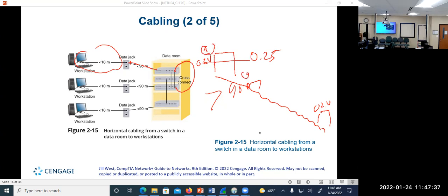Greater than 0.25, you know that is bit number one, and less than 0.25, you know that's bit number zero. But if you transmit a long way, the number one now only has 0.2, so we can think that is zero here, not one. That is degradation here, right? Degradation of the signal strength here.